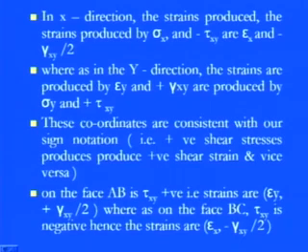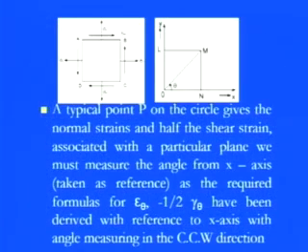That is, this tau xy is negative, hence the strains are also coming as the negative part, that is, epsilon x is the x coordinate and the y coordinate is minus gamma xy by 2. So, these are the key features which we simply got if the strain components are to be plotted. So, now come to the main feature.